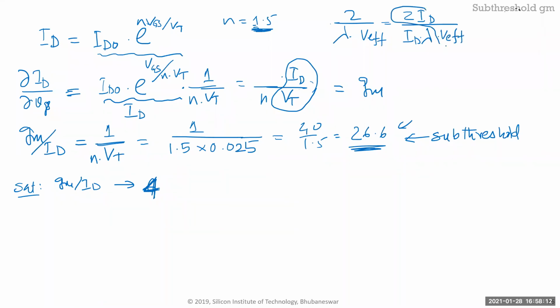What is this term here? We just derived it. It's GM. And 1 over this term is actually R naught, called the output impedance. So what I want is a high output impedance if I want high gain, and high GM as well, right? For high output impedance, like I said, you just change the lambda by changing the length. So you increase the length.